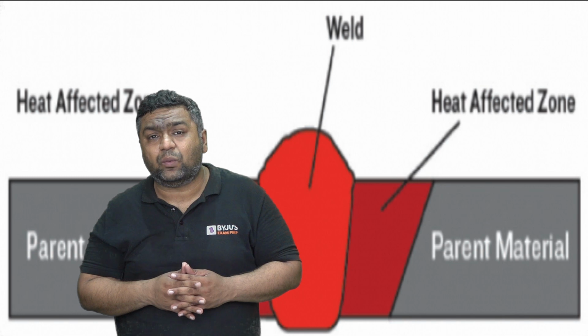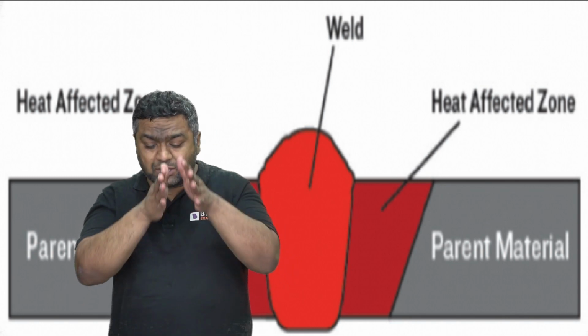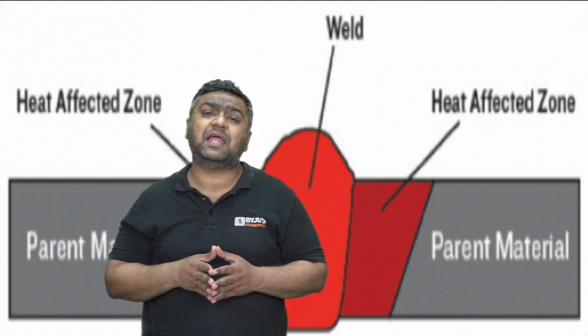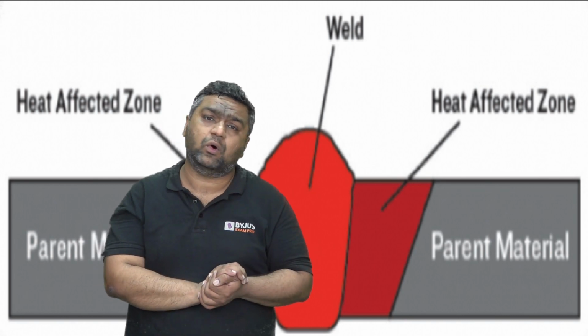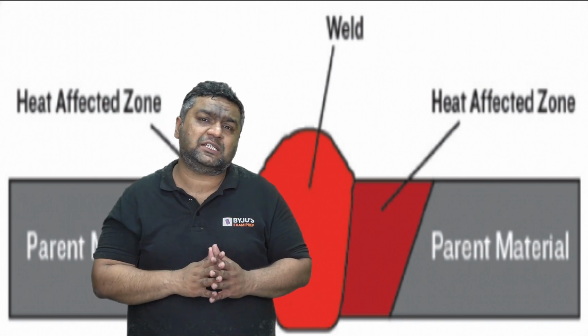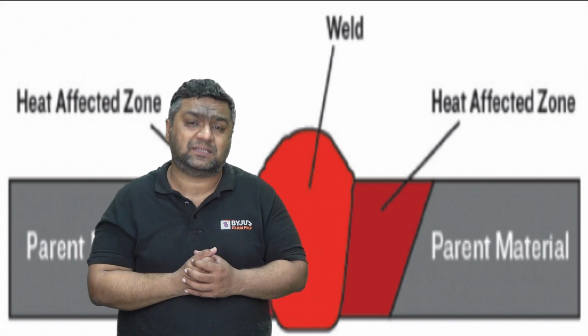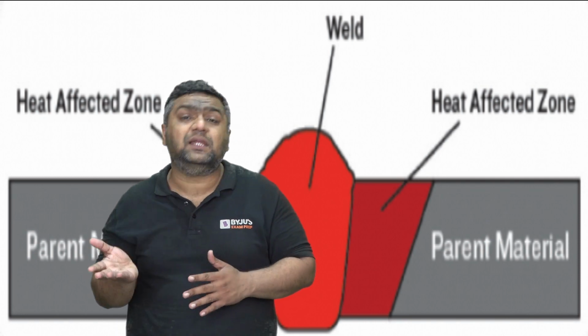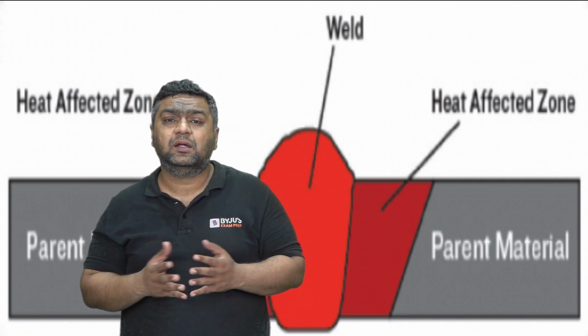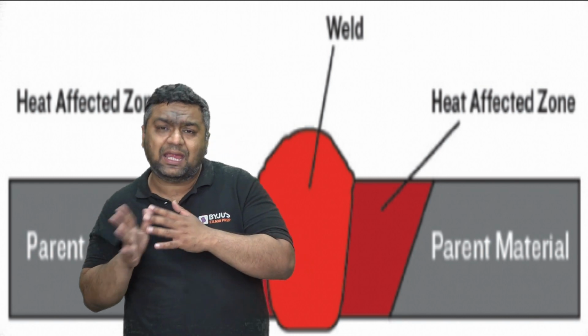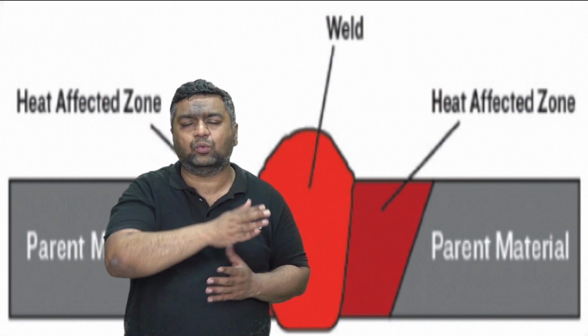After the welding is over, cooling happens. So the nearby region is feeling like some heat treatment process is going on. In heat treatment processes, which are done to improve the properties of the material, like annealing, normalizing, hardening, similarly, they have three things: heating, holding and cooling.